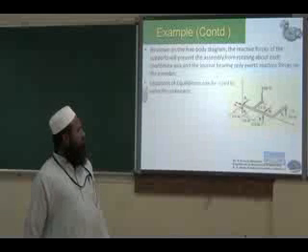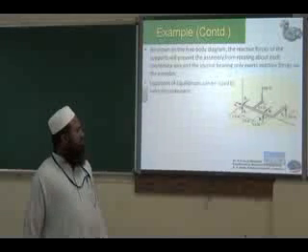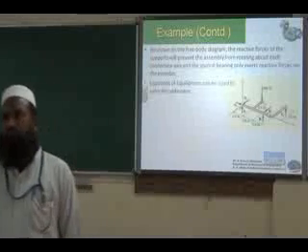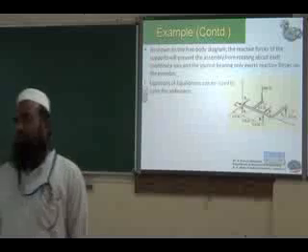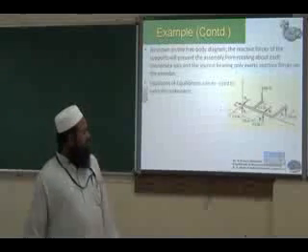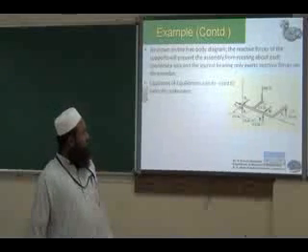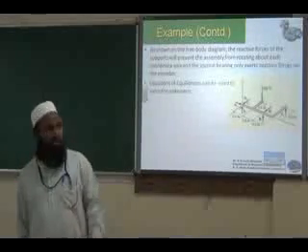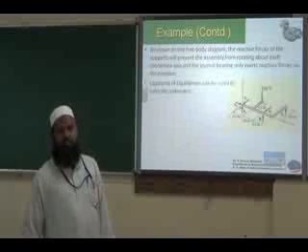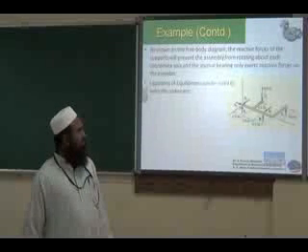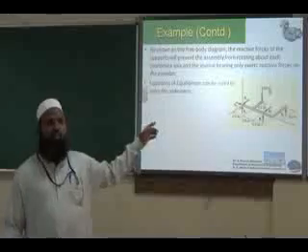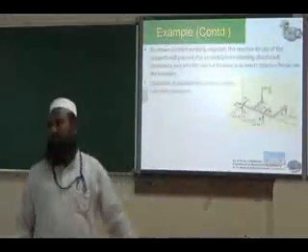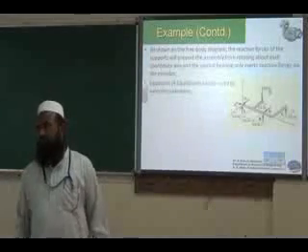So after showing all the reactive forces, now we have to find the unknown forces by using our equilibrium equations, sigma Fx, sigma Fy, and sigma Fz equals 0. Here if you see, there is only one force given. This is the applied force. 900 Newton is the applied, given force. Whereas the other forces are reactive forces due to the supports.